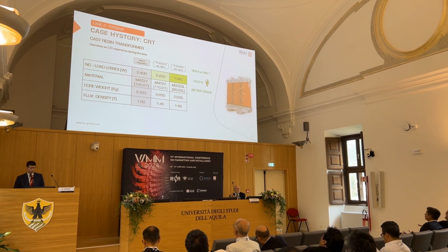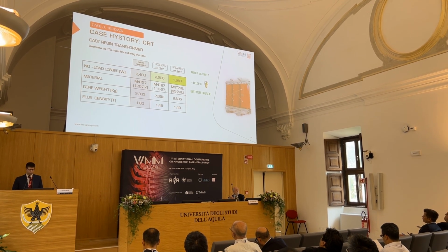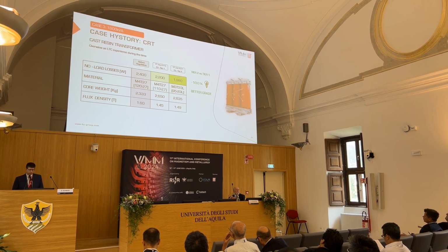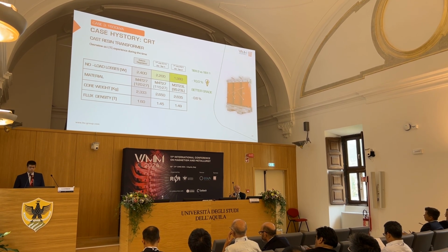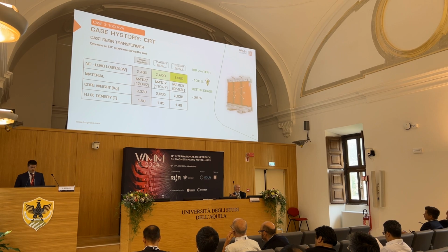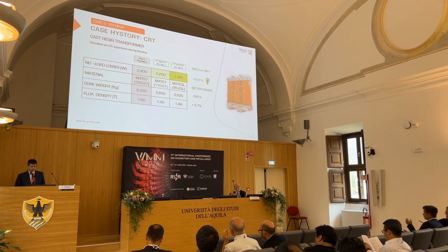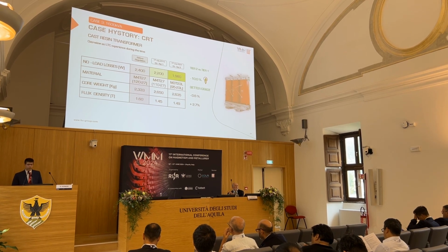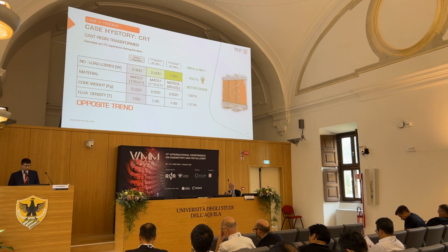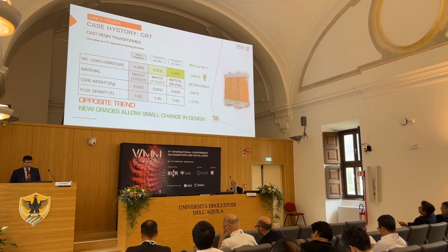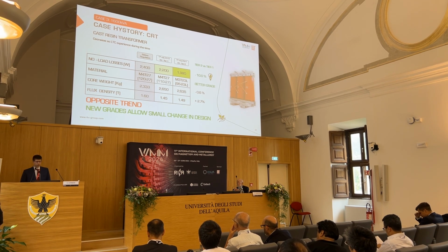So the losses move from 120 before the regulation to 95 in step 2. In this case, the weight is basically unchanged from the regulation, with only a small reduction of 0.6, but the induction is increasing again from Tier 1. So again, in this case we have a trend that allows a smaller core design and a more efficient transformer.